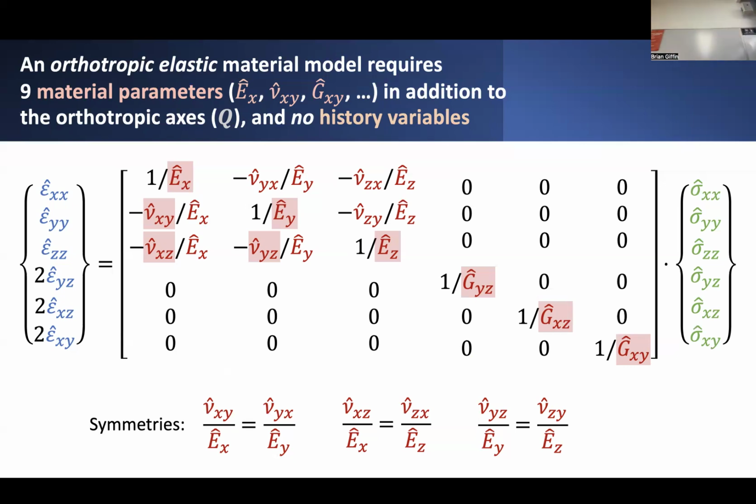You also need the shear moduli in these different modes of shearing, which differ depending on the orientation that you're shearing in. So you might have an XY shear, a YZ shear, and maybe a ZX shear, and all those different modes. So if you can do all those different tests, a total of 9 different tests, then you can come up with these different parameters. There may well be better ways to come up with these different coefficients, but in general, it's a little bit more work you have to do to come up with these values.